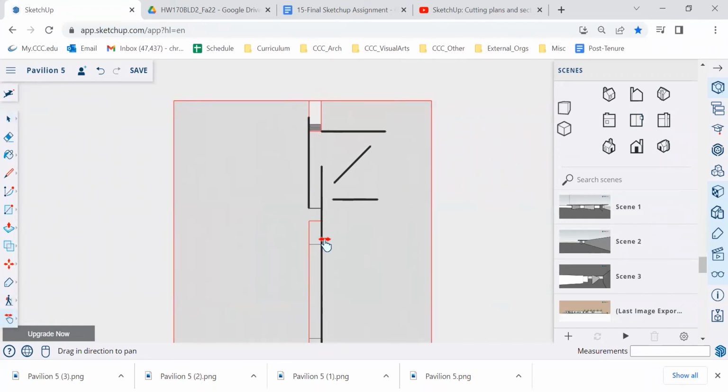It's showing things below, like the stairs. And the one thing that it's missing is showing the roof plan. Again, normally in an architectural plan, we would see that roof plane as a hidden or dashed line. Anything above the cut would appear that way if it's significant. So that's one problem with this.